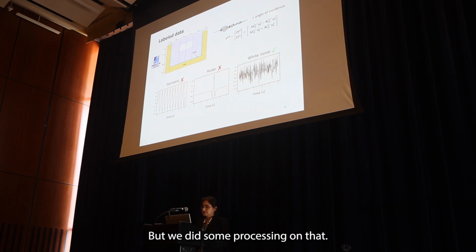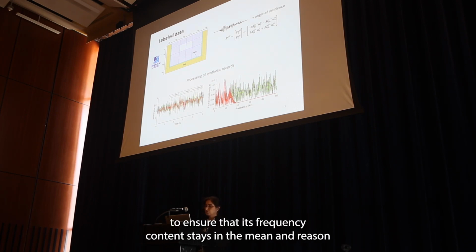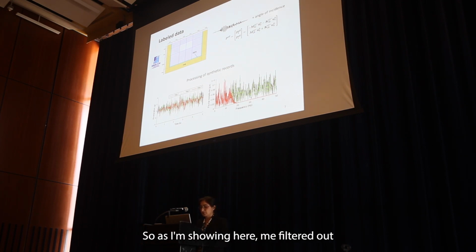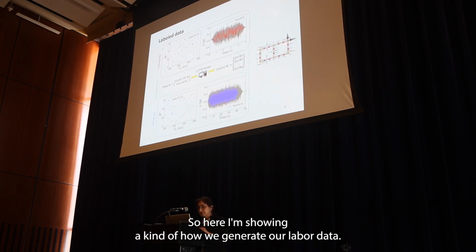But we did some processing on that. When we have the white noise, we pass it through some filters to ensure that its frequency content stays in the main region where our earthquake time histories are going to have frequency content. So as I'm showing here, we filtered our white noise to have frequency between 0 and 15 to 20 hertz.